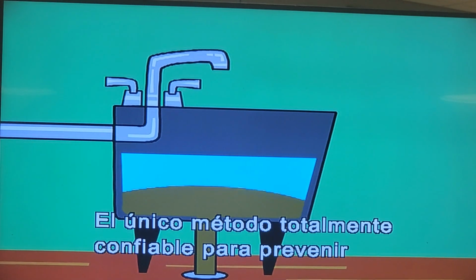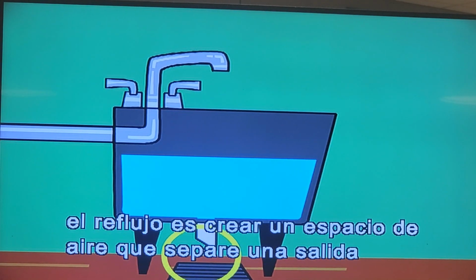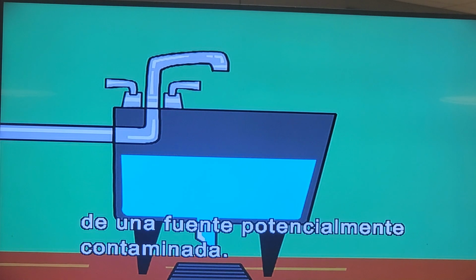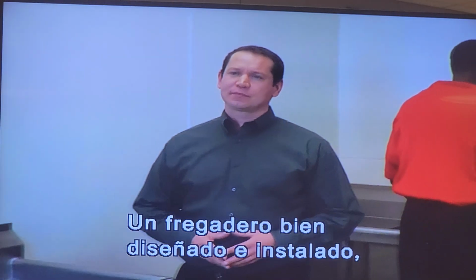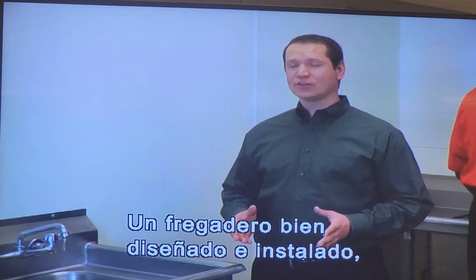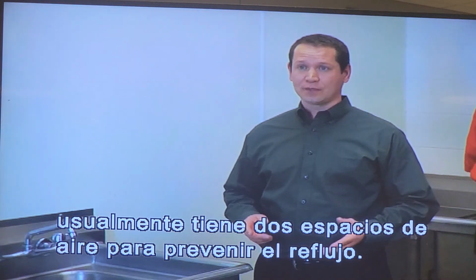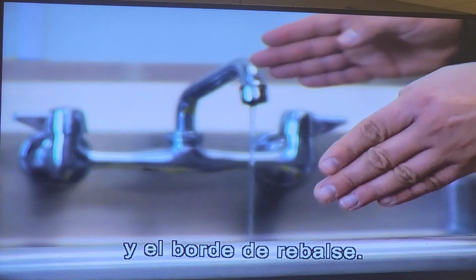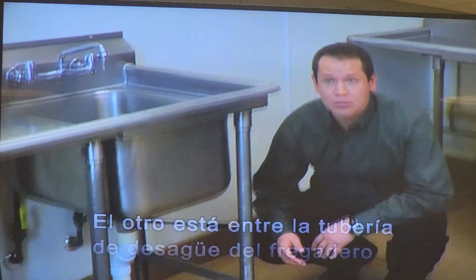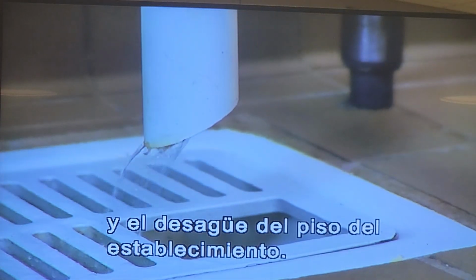The only completely reliable method for preventing backflow is to create an air gap. This is an airspace that separates a water supply outlet from any potentially contaminated source. A properly designed and installed sink typically has two air gaps to prevent backflow. One is the airspace between the faucet and the flood rim of the sink. The other is located between the drain pipe of the sink and the floor drain of the establishment.